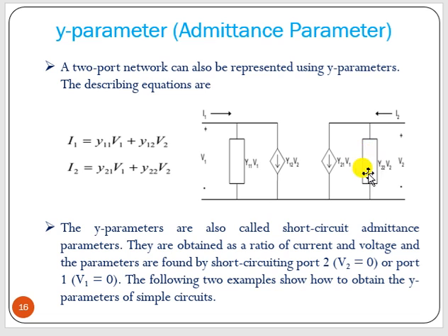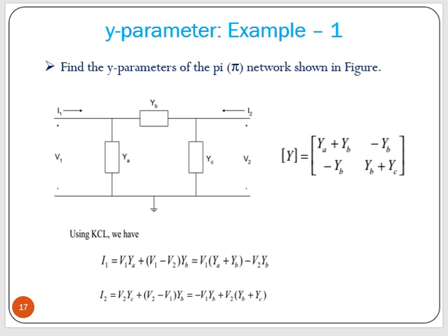And for the next, that is I2 into V2, I2 equal to what? Y21 into V1. That is the voltage controlled current source, and Y22 into V2, that is the I2. So this part is nothing but Y22 into V2. One current, another current, because I equal to YV. And this is nothing but a voltage controlled current source. As we are making V1 and V2 0, we basically call it the short circuit admittance parameter.